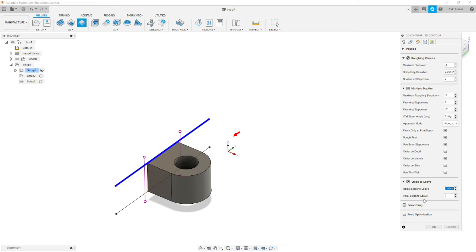So we're going to put in a negative 0.15. Okay, so an 1/8 inch end mill is 125 thousandths. So by putting in 150 thousandths, we're going to cut 25 thousandths wider than the cutter itself. That gives it some clearance for chips, clearance for mistakes, and clearance for coolant.